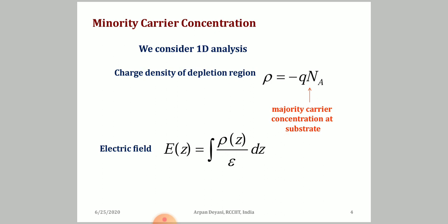And naturally, once I write the term minority carrier, it will be either depletion or inversion condition. Accumulation is never possible, because accumulation means upward band bending and there will be majority carrier accumulation. So I am going for minority accumulation, not the majority accumulation.